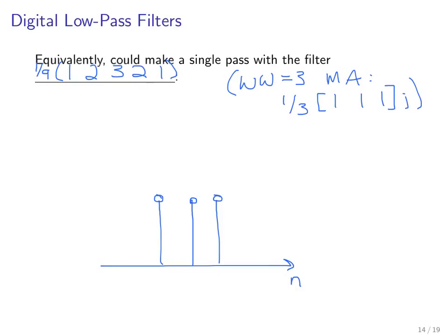So this is the original filter, which had amplitude 1/3 and then was zeros the rest of the time. That's the original moving average filter. This new one that we effectively get when we do 2 passes looks like this. It comes up to the same amplitude in the middle. It's triangular shaped, right? So that's a comparison of those 2 filters. You can see that the new filter with 2 window widths is effectively a bit longer, right? We have an extra sample on either side.